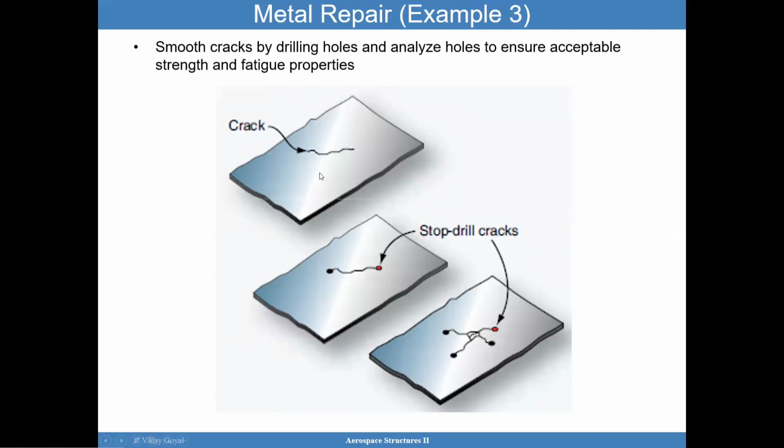Another approach that works really well if you have a crack is to drill a hole at each of the crack tips, so that now we have put in a stress concentration that's more of a hole rather than an infinite stress intensity factor. Hopefully that crack will not grow any further. So the important thing here is to ensure that the crack will stay in place.